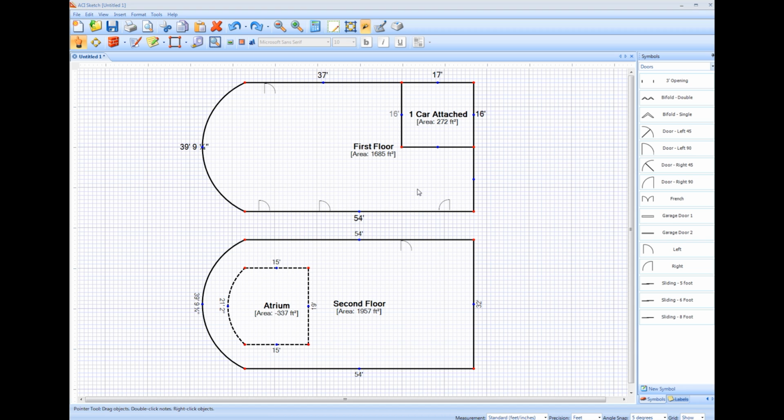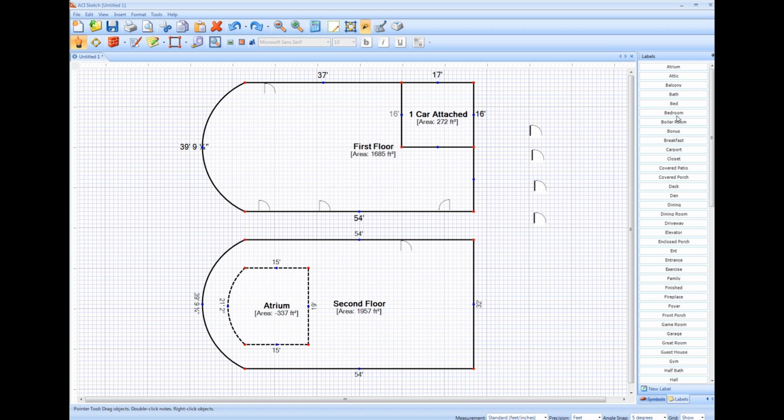To disable that or end the stamp mode, right-click. That turns off Stamp Mode. So once again, right-click, choose Stamp Mode, and begin left-clicking, and then right-click again to shake it off and stop Stamp Mode. This works the same with text labels such as bedroom.